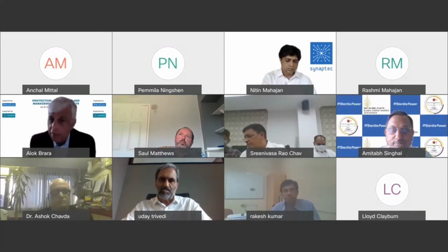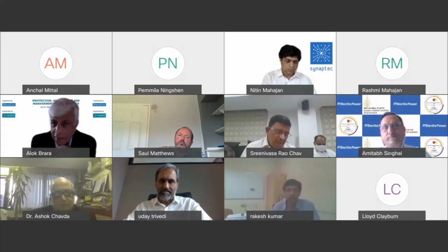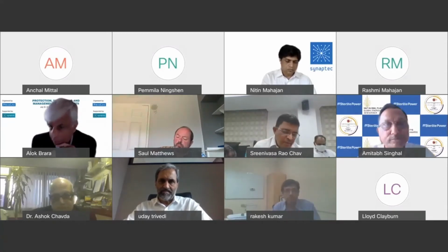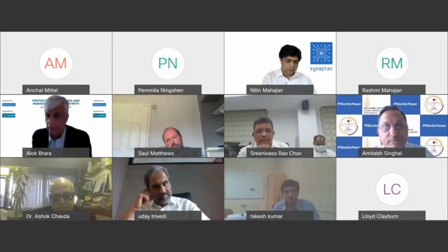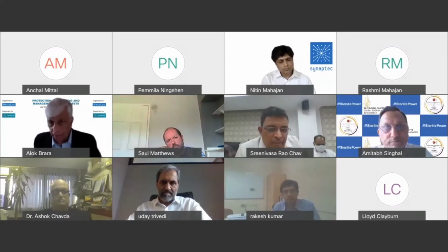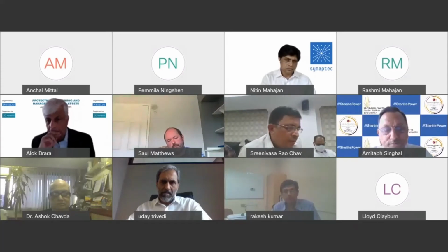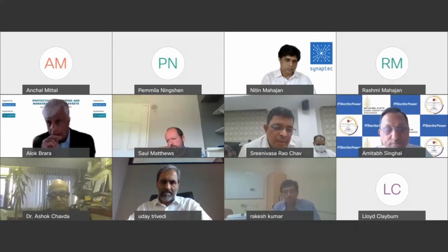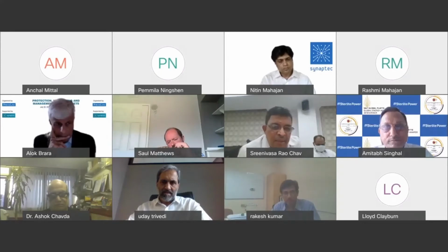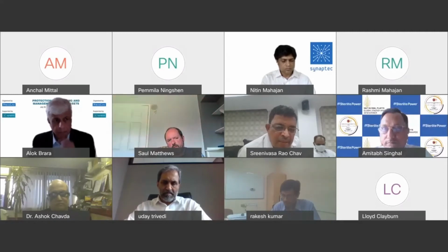Okay. Mr. Rao, are you able to speak now? Yes, sir. Sir, with GIS, we are entering all the coordinates of the power line. So in the GIS, we are able to find out the location. Next, during system studies also, we are using that grid map, for making an LILO of any line or finding the nearest substation. While doing these system studies, we are using that.